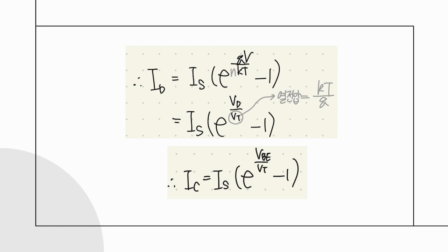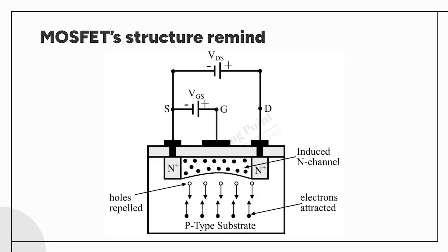As I described earlier, this can also be changed to the collector current of the transistor, which is completed by changing the diode current to the collector current. So, the diode voltage per thermal voltage becomes the voltage between the base and emitter per thermal voltage. The finished function is like this. Based on this process so far, if you have a somewhat simple understanding of transistors, you can derive the current formula of the widely used MOSFETs in earnest.